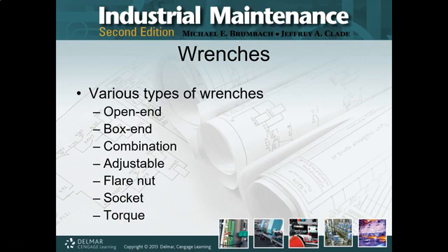There's also the adjustable wrench, and everybody goes, well, what the hell is that? Think a crescent wrench. A crescent wrench just happens to be a brand name, Crescent Tools, and Crescent was the one that came out with the first adjustable wrench. It's an open-end wrench, and it's really nice. It's handy. You got one tool for many different nut and bolt sizes. The catch is it needs to be properly adjusted in order to reduce stripping out our nut or bolt.